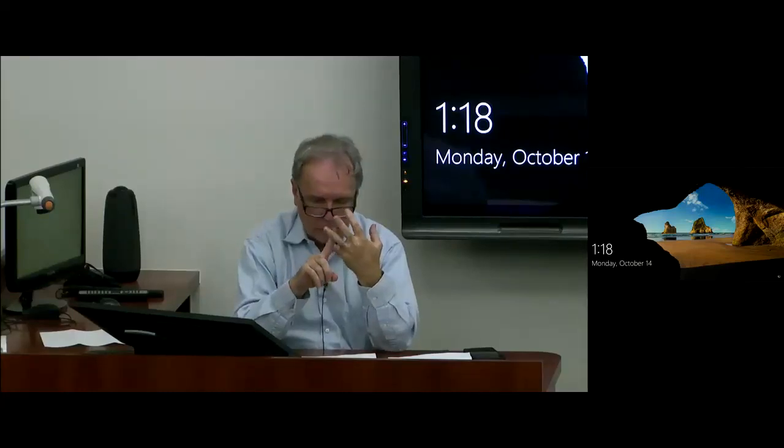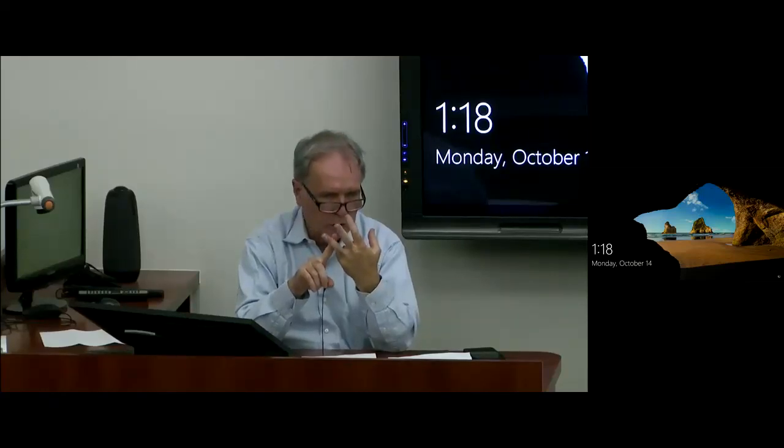I've started with high-speed steels, carbides, which are the workhorse these days, okay? We are getting better at making the carbides, so we make carbide drills, we make carbide milling tools, we do all these sort of things now. How can you tell whether your tool is a carbide or a steel? Tungsten is very, very heavy. So if you see two tools and one of them is more shiny, that's probably the steel one.